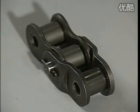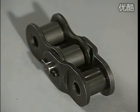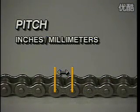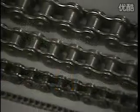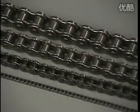For greater stability than the offset link, a two-pitch offset is often used. The two-pitch offset consists of a standard roller link and an offset link connected by a riveted pin. Chain size, or pitch, is expressed in inches or millimeters. Chain part sizes are proportional to the pitch. As the pitch increases, so does the chain strength, weight, and capacity.